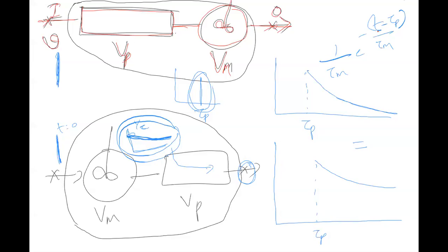No, they don't interchange, because it is just a delay. See, if I don't have the PFR here, your time is T. If I have the PFR here, whether it is first or second doesn't matter, because for you this is a closed system. Here the input is delayed, here the output is delayed. Basically, when you are standing here observing, it doesn't matter. So your time is delayed by tau p minutes.